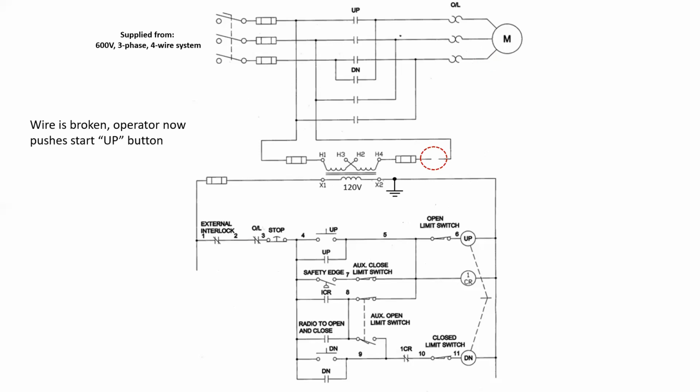We already looked at this one. What about that one? Wire's broken here. Operator presses the start up button. Well, nothing's going to happen, and that's because we have no power.